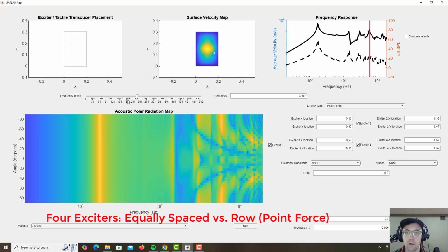That comes from the fact that for a long time, up until about a kilohertz, we have kind of nice radiation patterns, and then after a while it gets screwed up in here. The low point in the radiation is at 1600, so that's this mode roughly. Yeah, interesting. So we get a nice low frequency response. This peak could probably be equalized out, and we get a nice low frequency response followed by a pretty abysmal mid and high frequency response with a lot of sharp peaks and troughs.